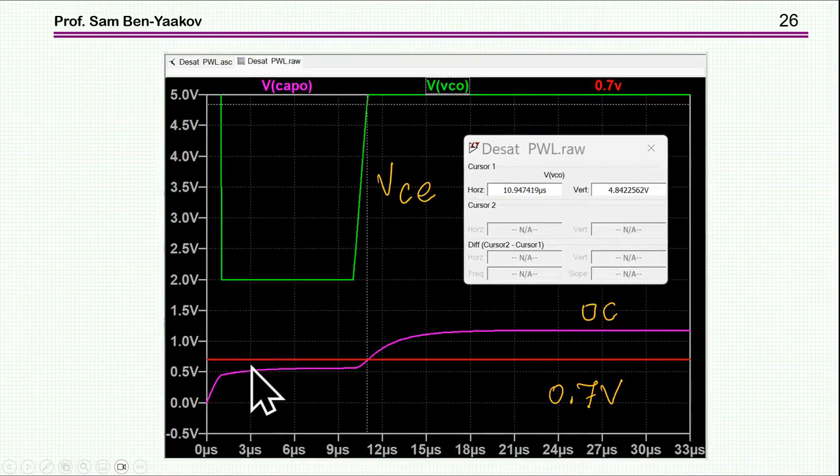Okay, so this is a case in which there is a short at the on instant of the gate. On the other hand, here I'm showing a case in which you start with no short, going down to 2 volts. So here is the blanking, and here I'm getting to a steady state below the 0.7 volt because I'm at 2 volt. And then here the voltage goes up due to the current, supposedly, and at this point it hits the 0.7 volt and the circuit will be activated.